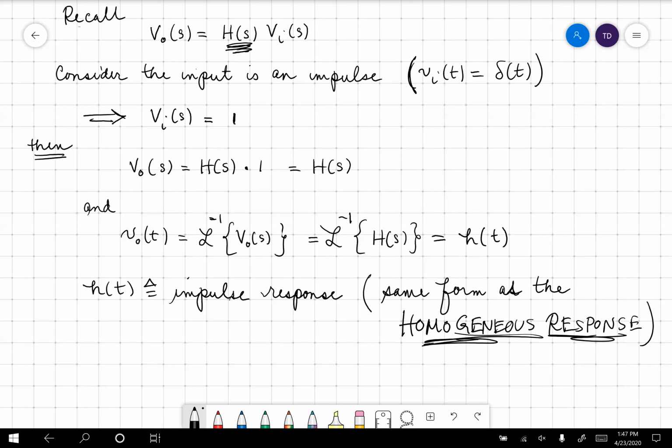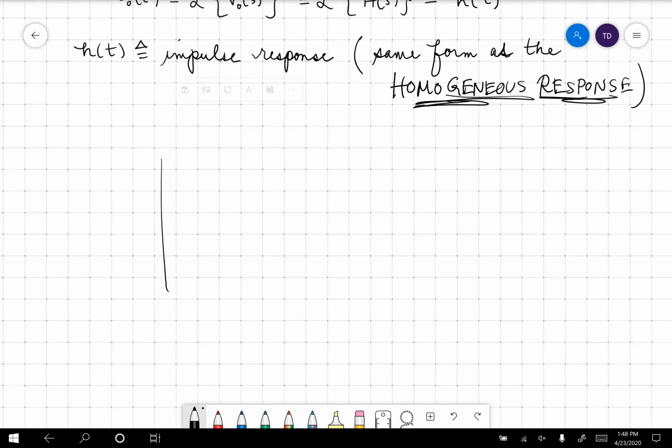So this is a critically important piece of information: you can take a circuit and insert an impulse. And by the way, we can do that. How can we do that? Impulses don't exist in the real world. This is how we do it. We just develop a real thin pulse, and it will mimic an impulse. You don't even have to get it to be real high, because all you're looking for is the form of the response. So you just make this more narrow, and you pop that into a circuit.